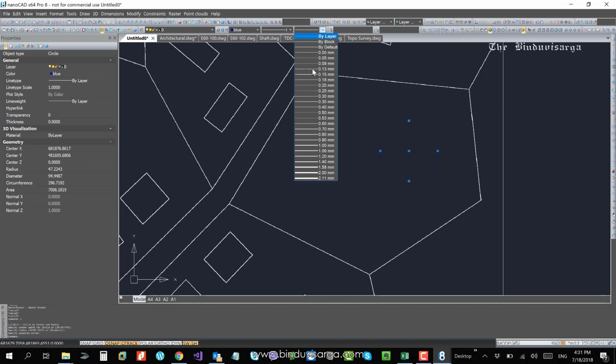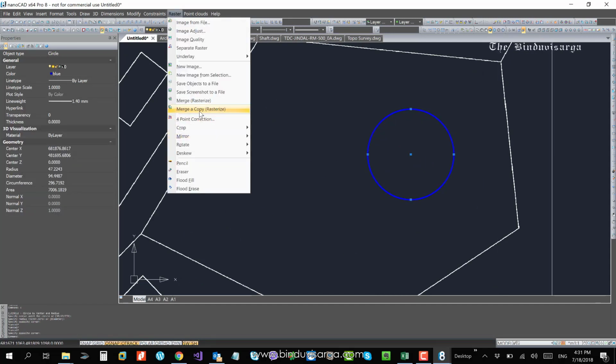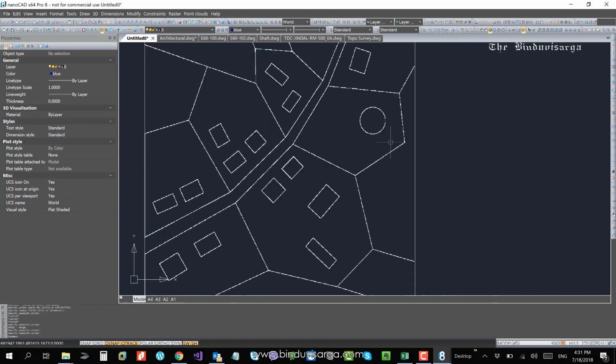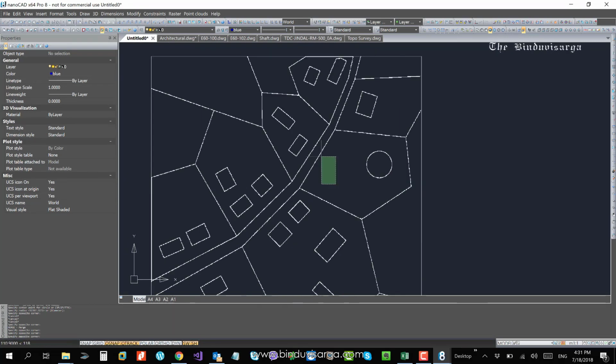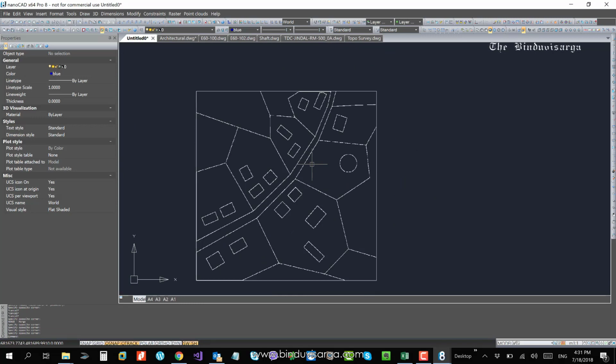I can increase the width to some extent, say to this, right? Now you select this, you need to match these things. I mean all the changes you will perform on this image. After that you need to rasterize. Once you click rasterize, this is now raster. So this circle is a part of this raster image now, and the rectangle is removed, right? So this is quite useful.